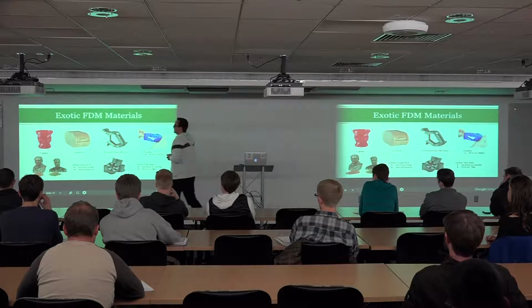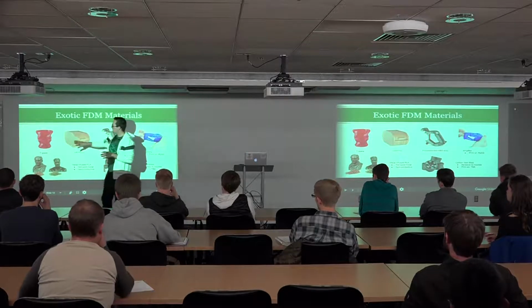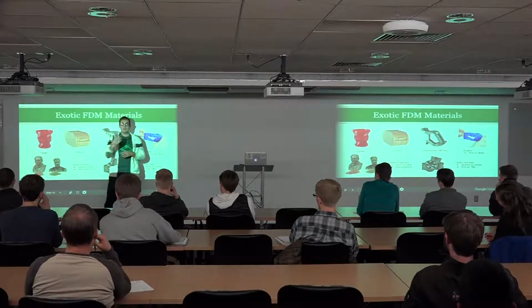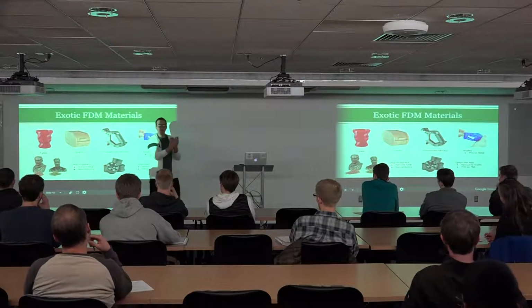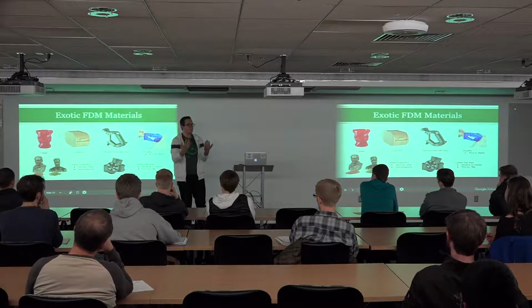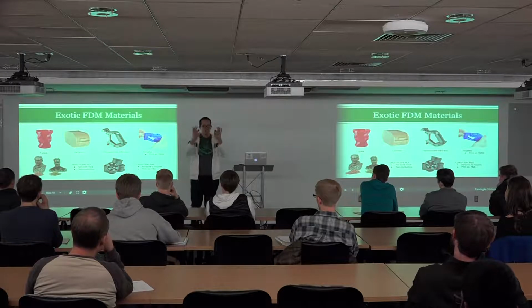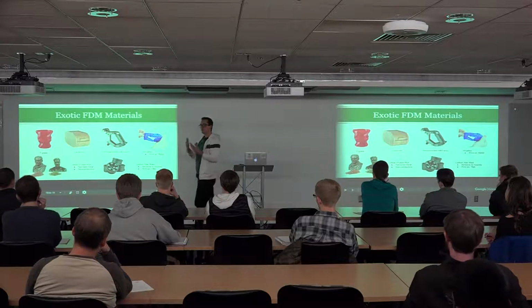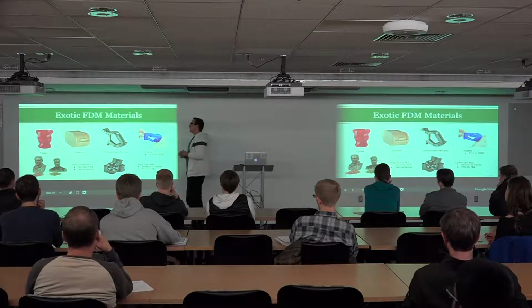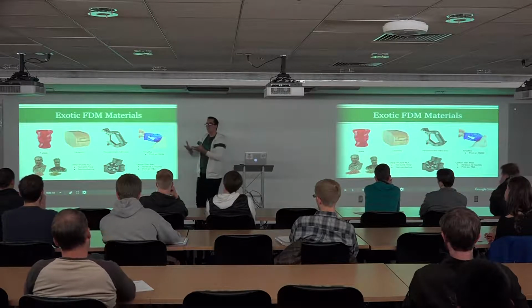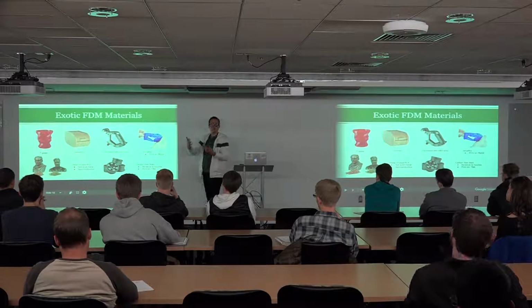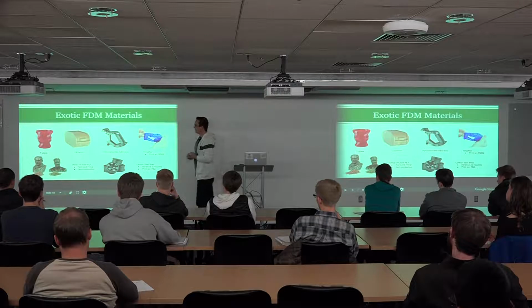Note though, no matter how clear the material is, once you build it out of layers, it's not transparent. You can't print glass or a window or something like that. You can print frosted glass because it's got all those little imperfections and things that make it opaque. So you could use it for a diffuser for a lamp or something like that, but you couldn't use it for a viewport or a window.